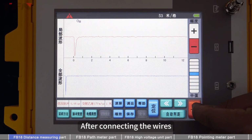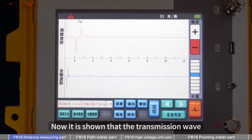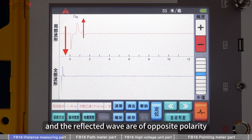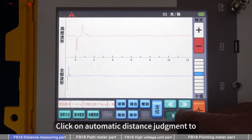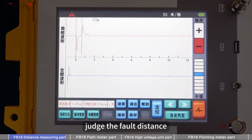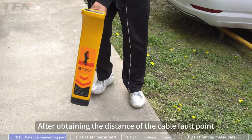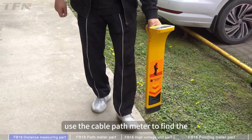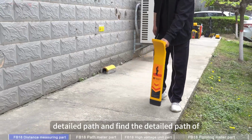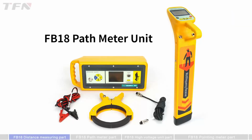After connecting the wires, press the orange sampling key to sample the waveform. Now it is shown that the transmission wave and the reflected wave are of opposite polarity, indicating that it is a short circuit fault. Click on automatic distance judgment to judge the fault distance, and the fault distance is 32 meters. After obtaining the distance of the cable fault point, use the cable path meter to find the detailed path of the cable at the measured fault distance of 32 meters.